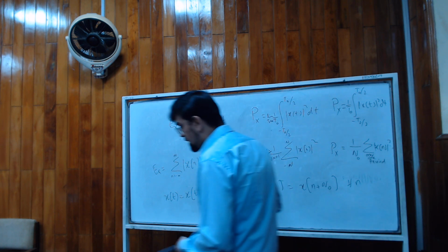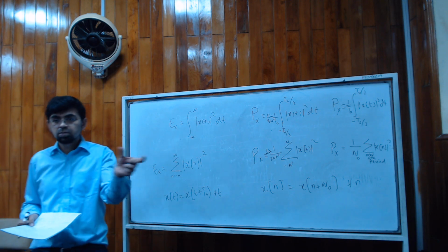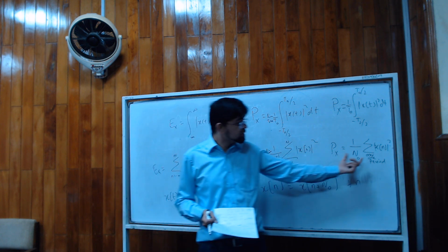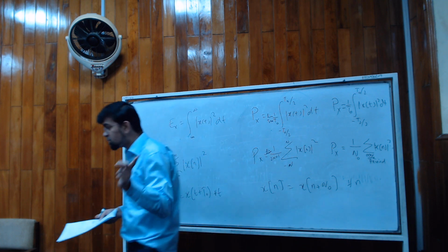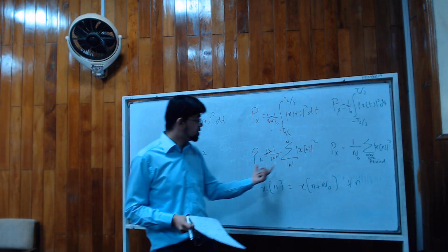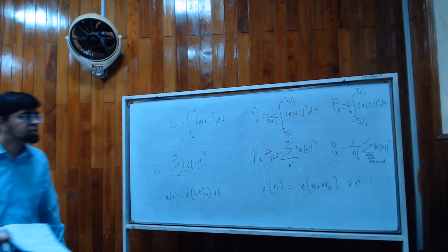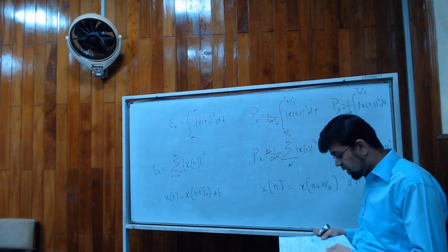The indices are hard to write for discrete time if you don't know the exact period, because it could start from anywhere. So for convenience we just say you take one whole period, sum up all the values in that period, absolute square, divide by the length of the period, and that is an easier case compared to using a limit. 0 से N naught का लिख सकते हैं वैसे. बिल्कुल, you can write that.